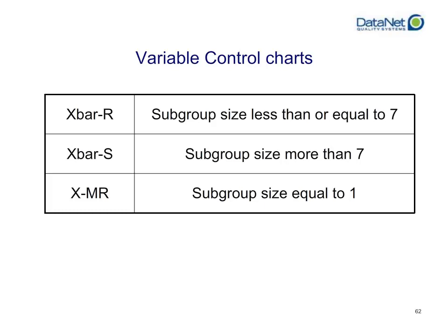As you'll find when you go through some of these examples, while most people tend to focus on the X-bar chart, which is your average value, the volatility of your process is captured more in your R chart, your secondary chart, which illustrates just how capable you are of producing product consistently.